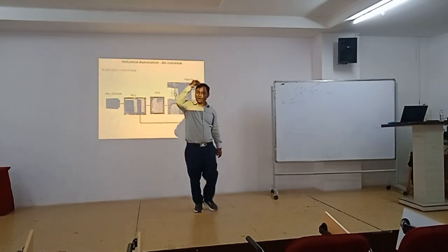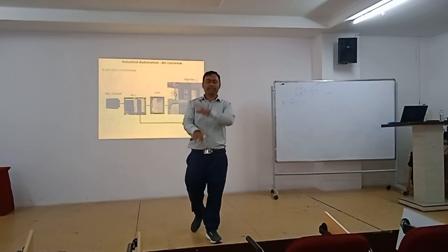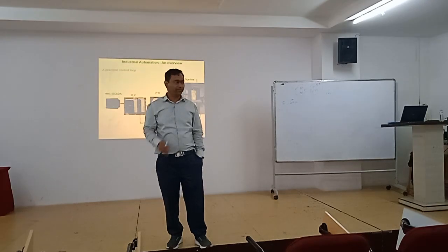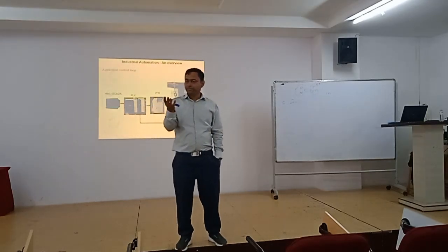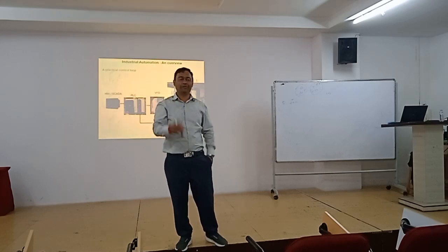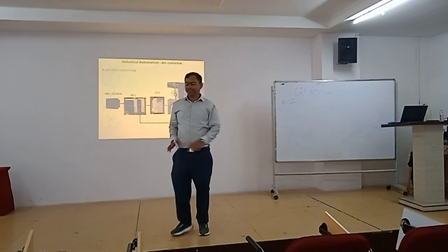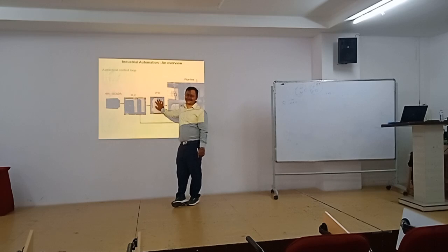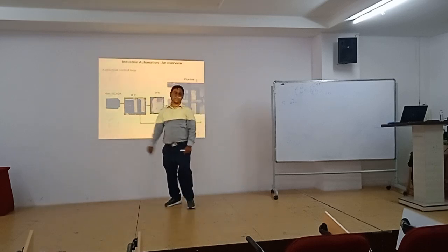So in almost all cases, right? Now next, you have to maintain the pressure. Then same, you measure the pressure. Accordingly, you increase or decrease the motor speed. So everywhere, motor speed is coming into the picture. Correct? And there is an induction motor, and the induction motor speed you are controlling by the VFD.